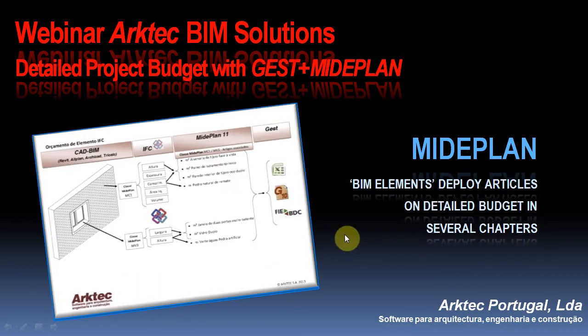Here we have the same process but applied to one BIM element, in this case a wall element, that is connected by a code to Midplane, and Midplane deploys several items of the budget associated with resources in the JS database. As we can see, each item looks for some specific measurements. So this process is programmed in Midplane.